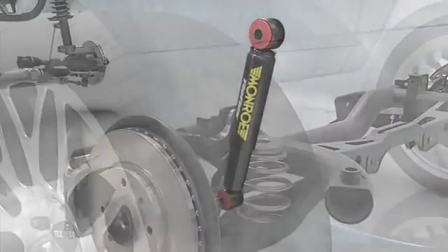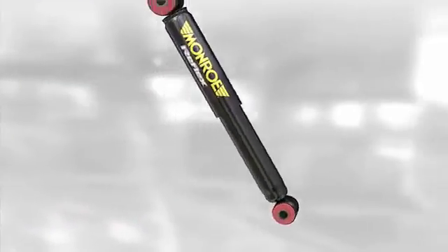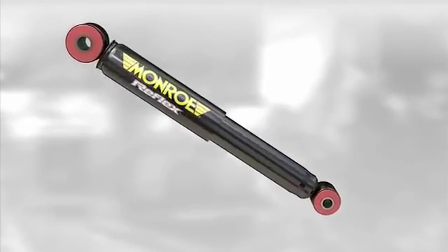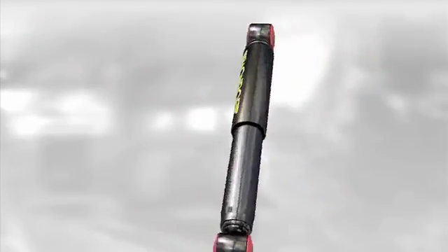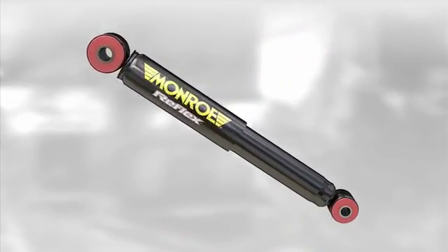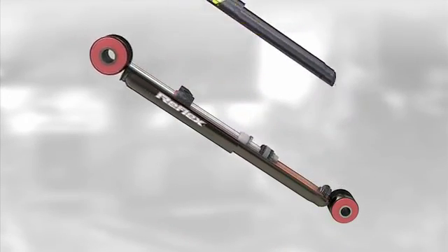Shock absorbers today are hydraulic devices, i.e., they work on the basis of oil flowing through valves, the damping rate of which is sensitive to the speed of the piston. Therefore, the faster it moves, the more resistant the shock absorber is to movement, thus becoming more rigid.